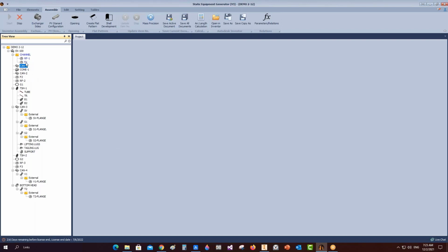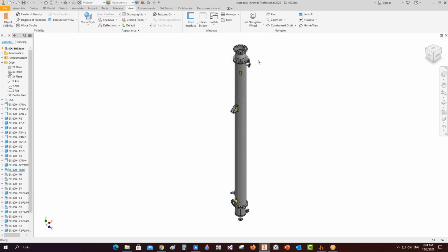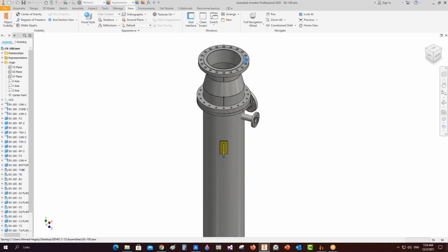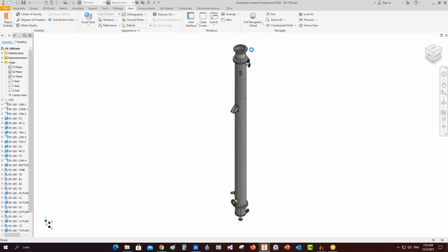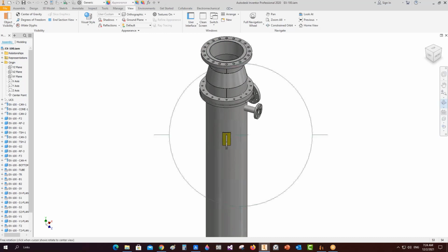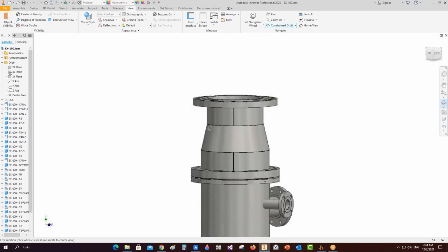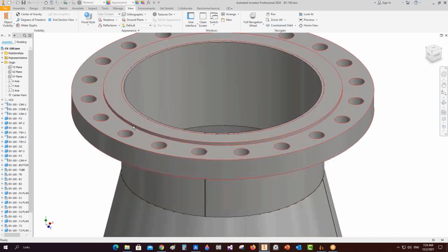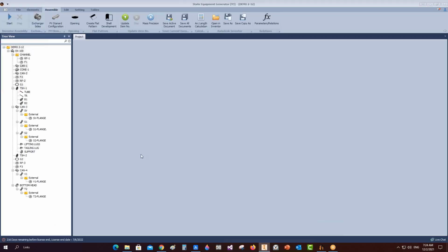Sorry, I selected F1, not rest face 2. So we made those elements only on this assembly. Sorry for that. Okay, so we will need to delete this group again and define it again. As you can figure, now we have this group, the rest face with the flange, but we need to make an update. So from group, we will delete this group, sorry,